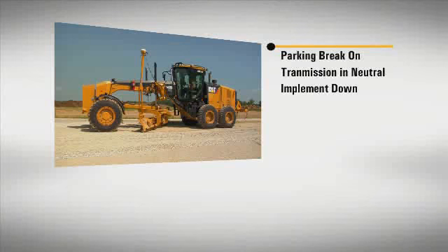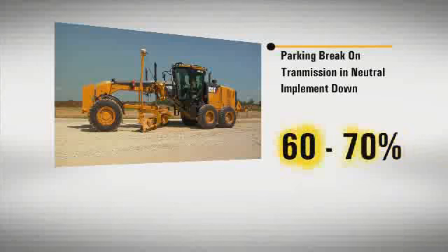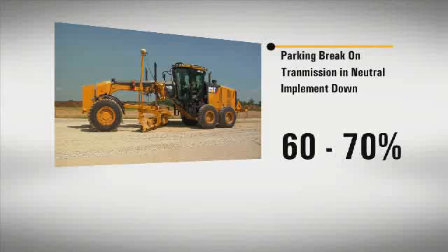When the high-speed setting is enabled, regeneration is initiated while the machine works as soon as soot levels reach approximately 60 to 70%. The advantages of low-speed regen are that it takes less time and uses less fuel than high-speed regeneration. The maximum number of minutes required by the system for low-speed regeneration is 20 to 25 minutes to clean a full diesel particulate filter. High-speed regeneration times will vary. In light work applications, however, some machines may not need regeneration for several shifts.